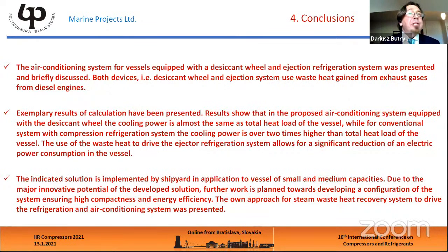45. Yes, 45. 30 or 40? 30. 40. No, if you have 45 centigrades, it is problematic just because probably you are operating under off-design operation conditions, and you should carefully study whether such operation is possible. It is possible, but probably your coefficient of performance is not very good. So condensation temperature is very important.